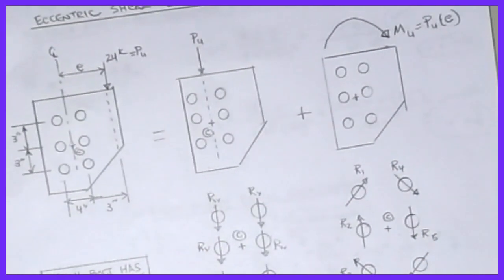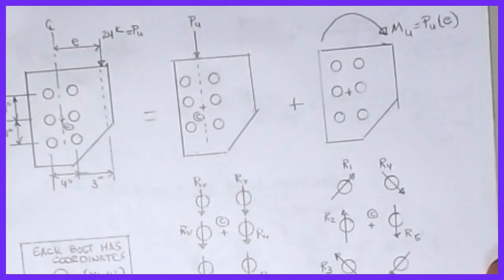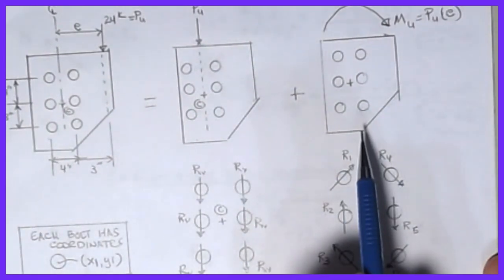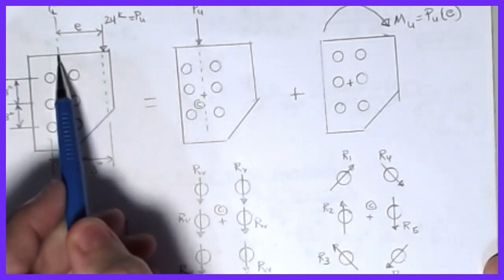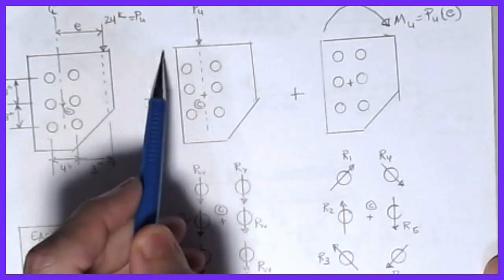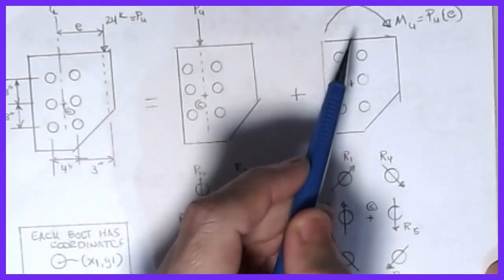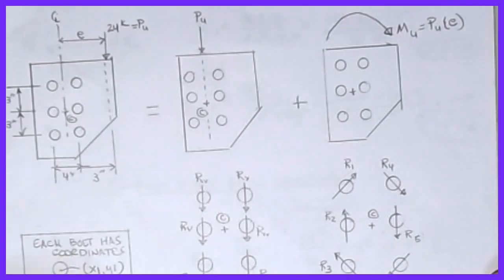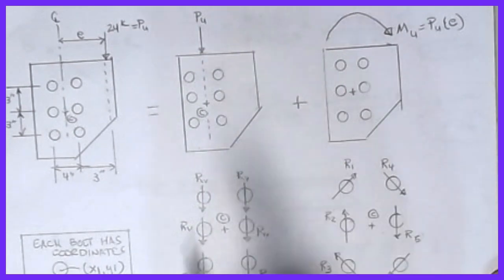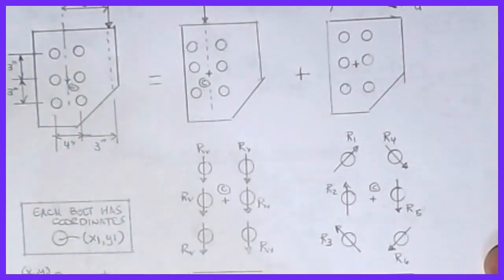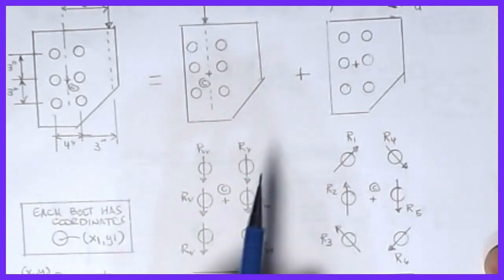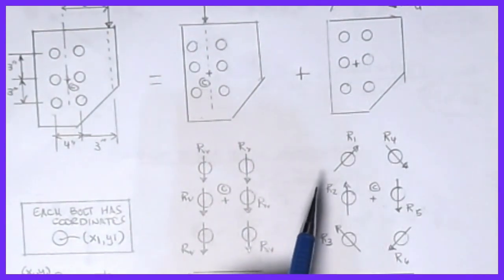The one that gets a little bit different, and makes things a little bit more complex for analyzing, is the second half of the equation. By moving this force back to the center of the pattern from statics, to get us the case that we know how to analyze from before, I do introduce a moment into the connection. This is the rotational characteristic of what's happening, and so this whole plate is wanting to spin about that same center point of the pattern. When I do that, each bolt works a little bit differently to provide that moment, or to be able to resist that effect.